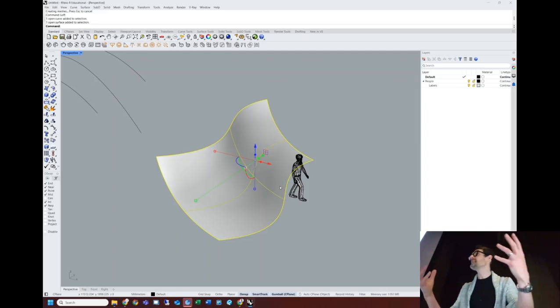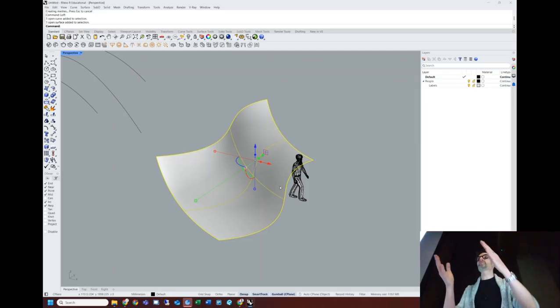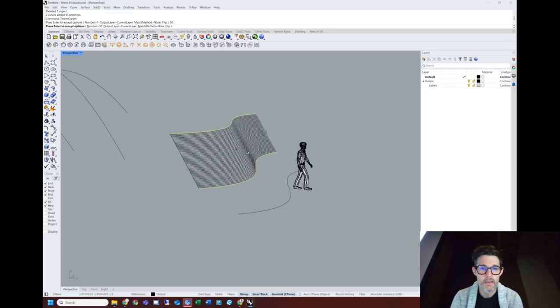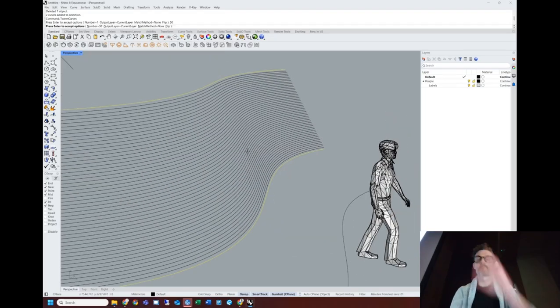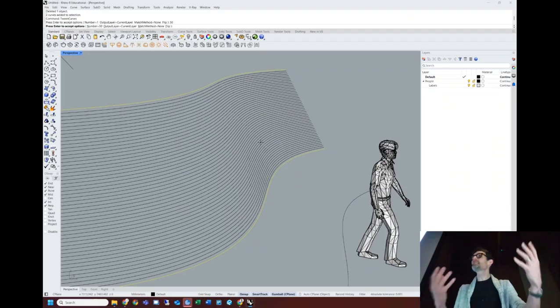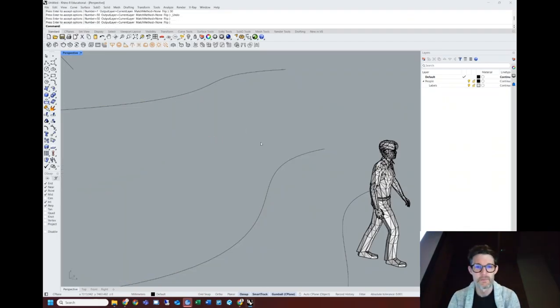And when I say interpolating, what I mean is, just imagine a curve. In fact, I can even demonstrate this. Here are 2 curves. If I type in tween curves, and I want, like, I don't know, 50 of them, each one of these 50 curves kind of blends between the 2. All the surface is just a multitude of curves. So tween curves and making a surface, they end up giving you the same kinds of things.